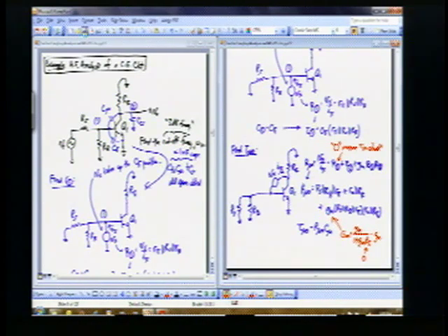Just want to make sure I've written down a lot of the things that I said. Okay? And so let's now find the last time constant that we have here. We've covered C pi. We've covered C mu. Now the last capacitor we have to cover is CCS. And actually I should think of it as node. The last node we have to cover is node 2, for which the total capacitance at node 2 is CCS.